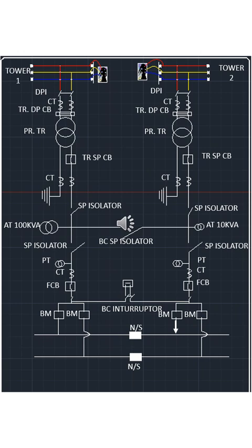And another thing is protection. Protection is also very much important. If there is any fault, what type of fault? It may be a dead earth fault, or it may be an earth fault at a distant place from the TSS, where the current is so low it is not sufficient to trip the overcurrent relay. At that time also the distance protection relay will protect, and the relay will feed the trip circuit of the circuit breaker, and the circuit breaker will trip.